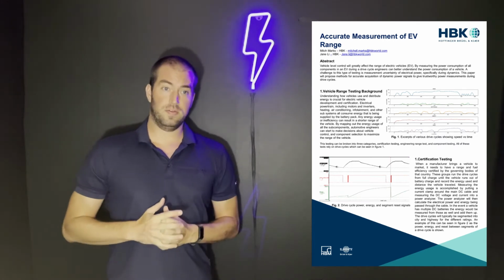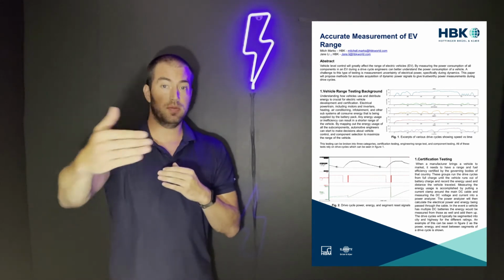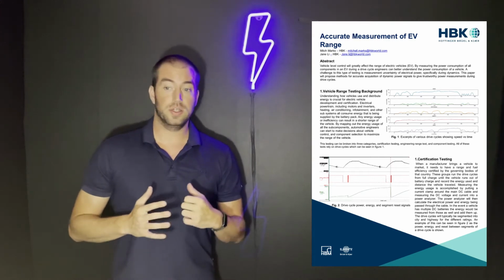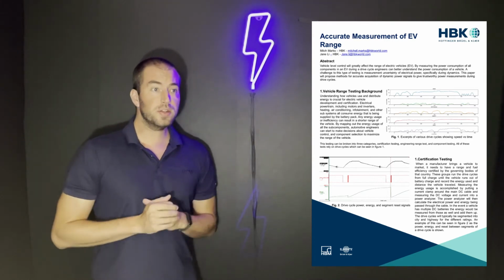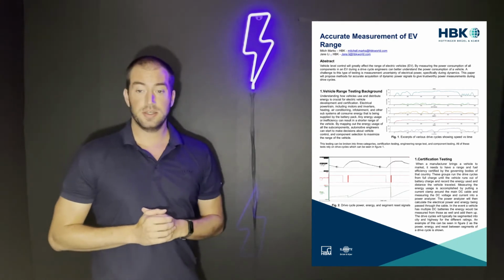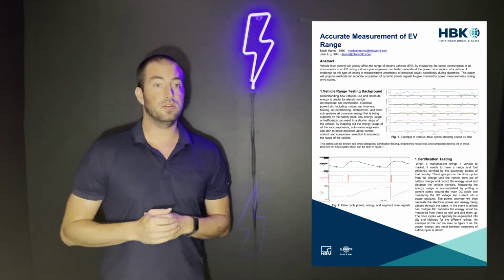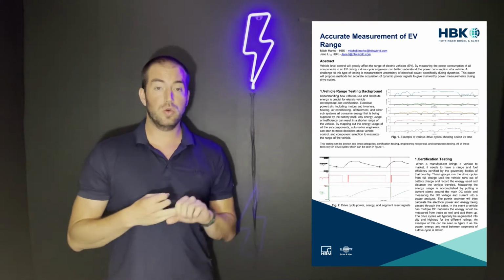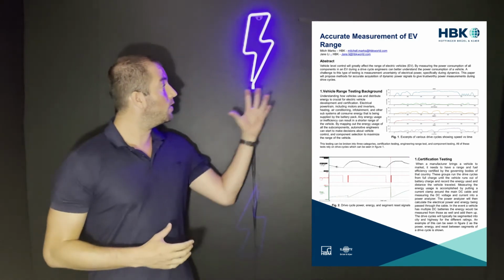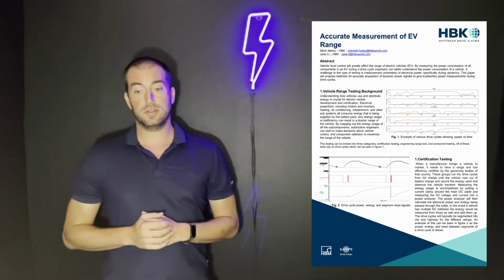Now you don't just take the vehicle to the big show. You want to calibrate the vehicle first. You want to determine the good components and the bad components, and make changes so you can maximize that range. This is what we call the engineering range test. The engineering range test is going to be the exact same as the certification test, except now we're going to instrument every possible power sink in the vehicle. We're going to look at the heating, the cooling, the battery temperature regulation, the infotainment. We're going to look at how each component consumes electricity throughout these drive cycles.